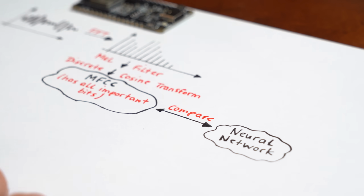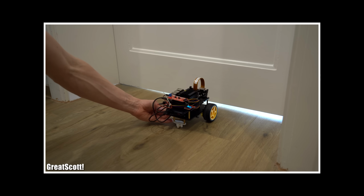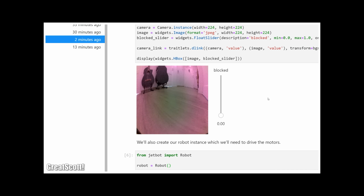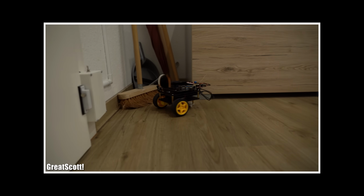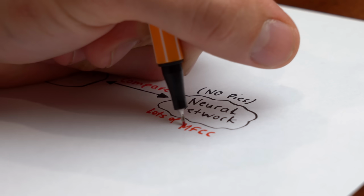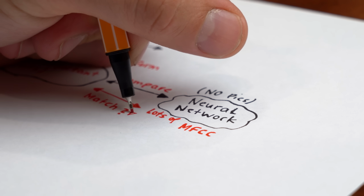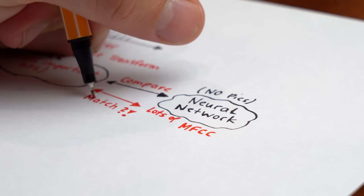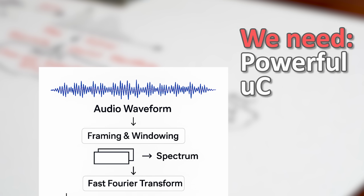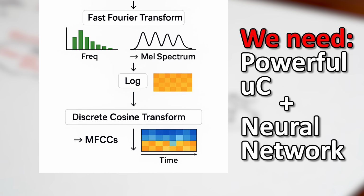These then get compared to a neural network, which is similar to the one I created myself in a previous video. There I took tons of pictures of my corridor and labeled them as blocked for my robot, and thus by comparing those to its live camera feeds, the robot drove around on its own without hitting any walls. Now of course, the voice command neural network does not come with pictures, but instead with tons of MFCC that all represent different words, and if one is similar to our MFCC turned audio waveform, then we know what word or phrase got spoken. So long story short, voice recognition is not only complicated, but for it we also need a fast and powerful microcontroller to do all the MFCC stuff, and also a pre-made voice-trained neural network.